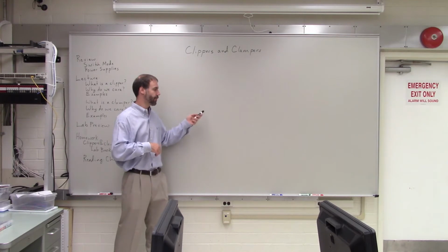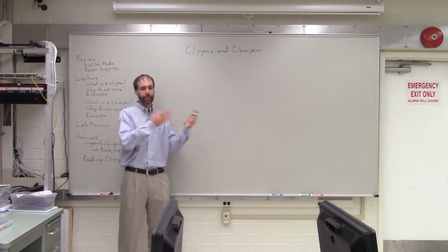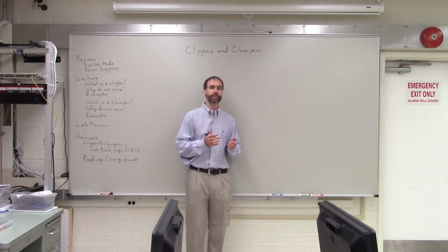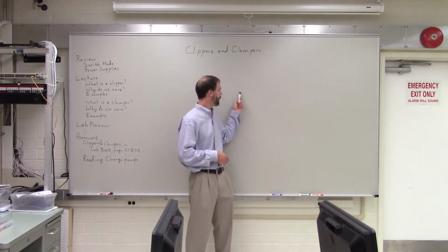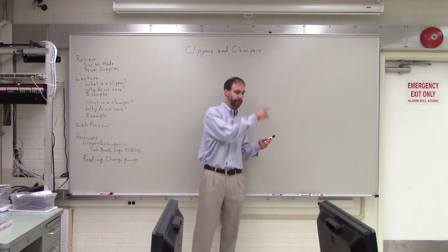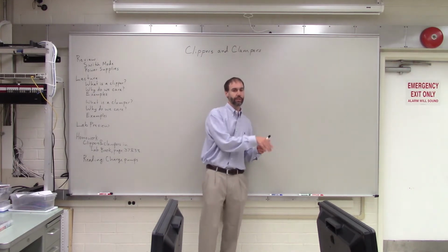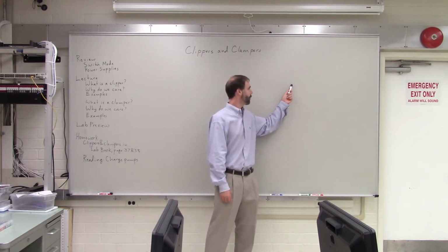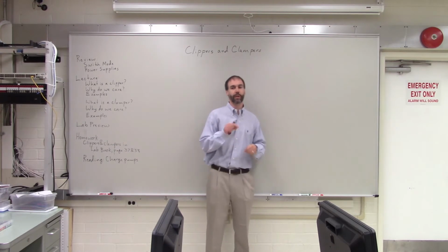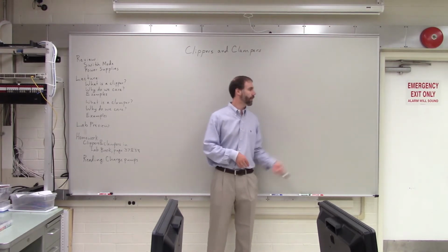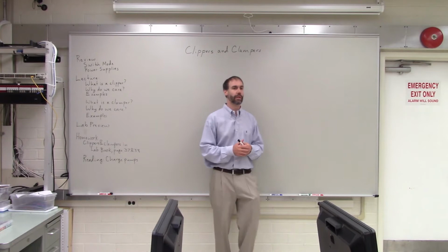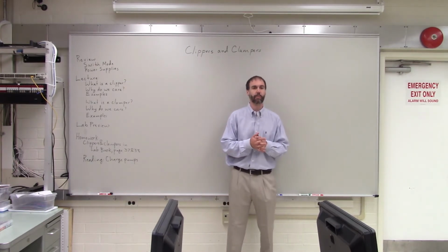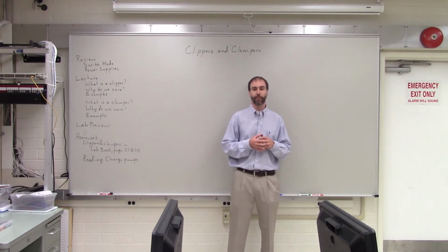That takes the low voltage AC signal and only gives us the positive part of it. And then what comes after the rectifier? Filter. Yeah, the filter, exactly. So that takes the rectified DC voltage, which has big changes, and it smooths it out a little bit. And it's still not a perfect wave, but it's a lot smoother. It's still got a little bit of ripple. And then what is the last component that gets rid of all that ripple? A regulator, exactly. So that's the typical linear power supply. We've been studying that for a while.